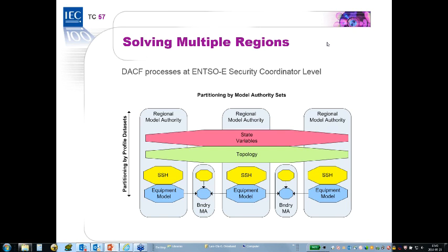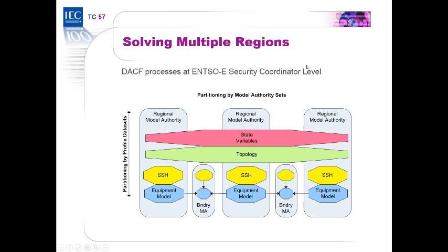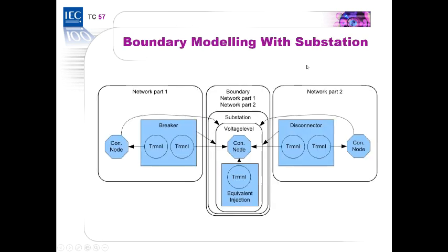With a manual equivalent, you may want to have, for instance, a generating unit representing a couple of smaller units. That's still a generating unit, so you want to keep it as such. So we have a flag on generating unit, I don't remember the name now, that allows you to do that. Aggregate unit, I think the flag is called. But you saw in my presentation, equivalent injection, that guy I think is from the equivalent package. So there is a model in CIM that supports the result of a network reduction.